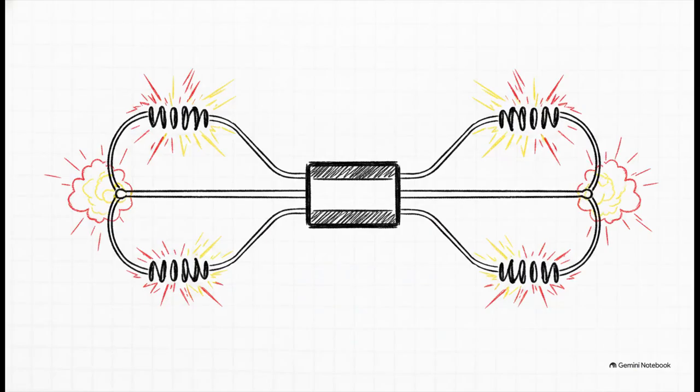So, let's take all this theory and apply it to a TCSC, a thyristor-controlled series capacitor. Physically, you've got a capacitor placed in series with your transmission line. But to actually manage and control it, you connect an inductor in parallel to that capacitor. Now, think back to what we literally just talked about. You are suddenly introducing parallel components into a massive, high-voltage transmission system. Based on our basic circuit theory, that introduces some very immediate, very real dangers.